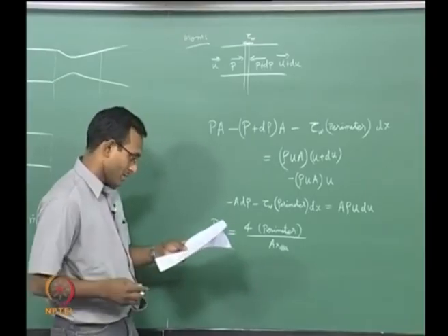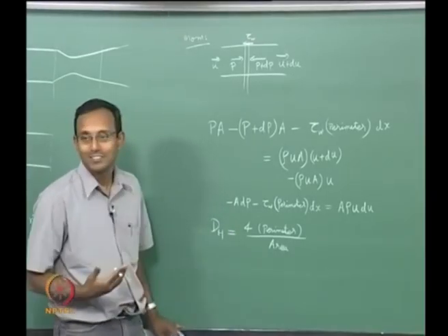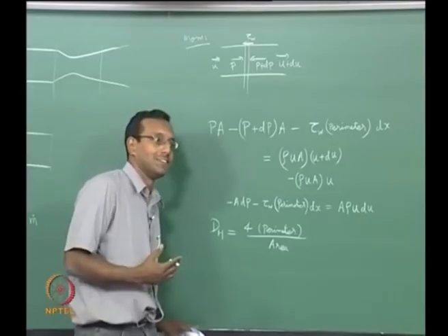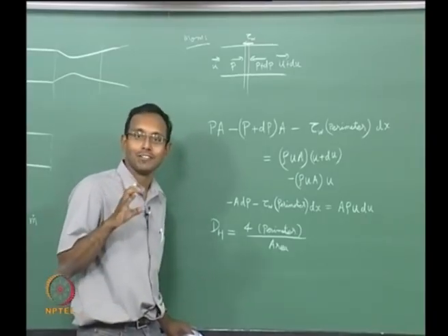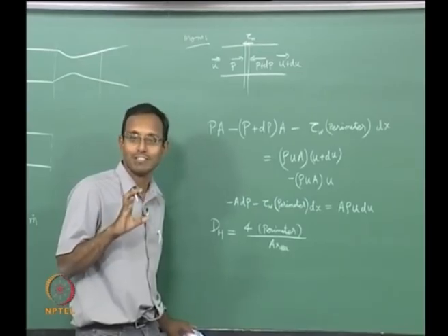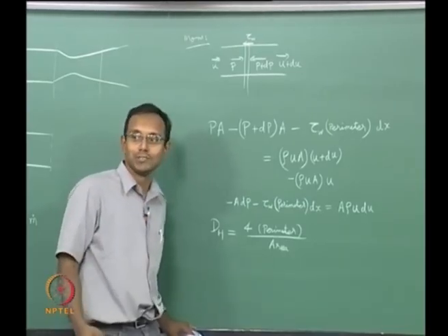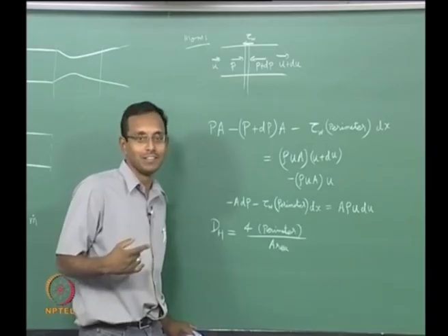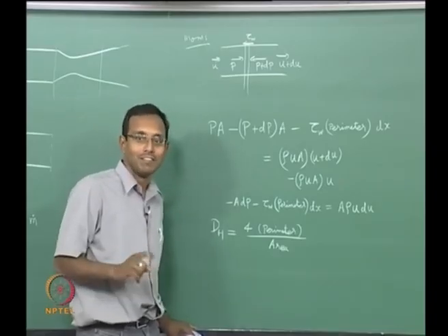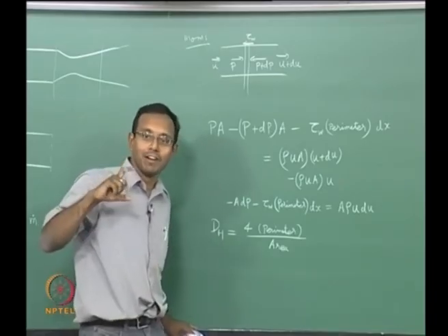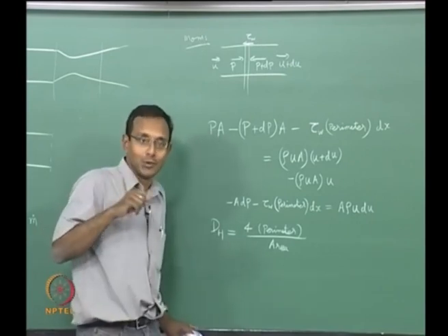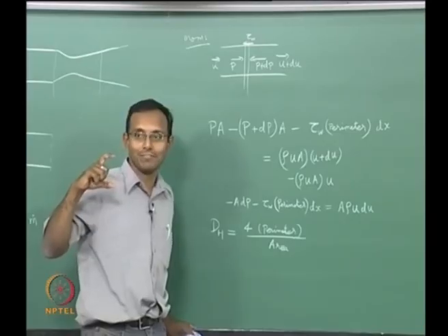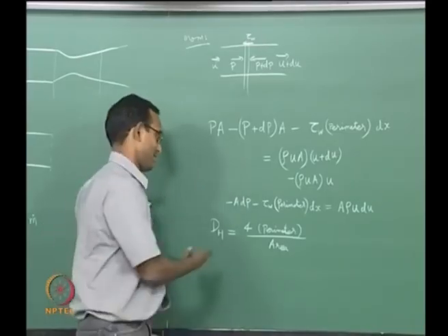How do we get to this 4? This is the engineering way of looking at things. Not all ducts will have a circular cross section. So, engineers used this and finally found that if I use this formula, I will get the diameter for my circular duct naturally, and if it is a square duct, I will get the side of that square. Just see that directly.